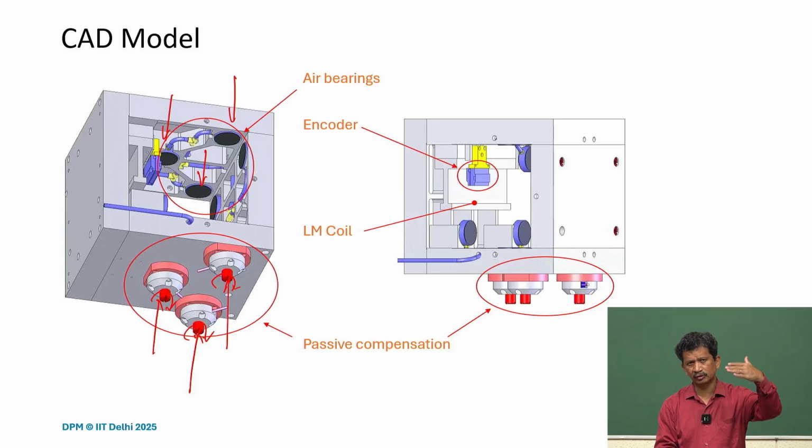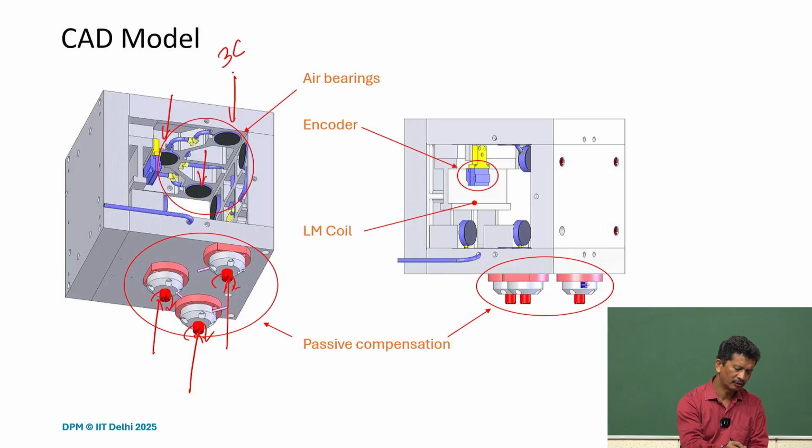So yeah, a similar kind of arrangement. The only thing is on the top the bearings are directly mounted, and of course we can have a fixture so that it can self-align, so ball and cone kind of fixtures. At the bottom we have that flexure. We can say it's a compliant mechanism, but basically it's disc springs. We are using disc springs. So three constraints, very good.